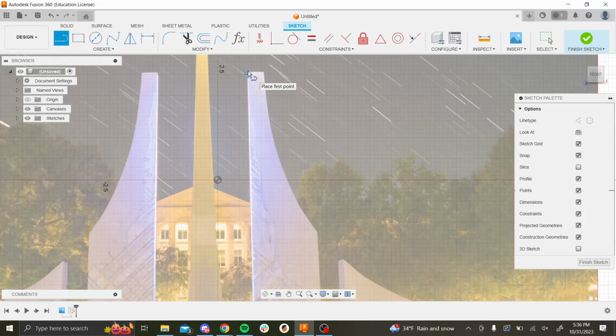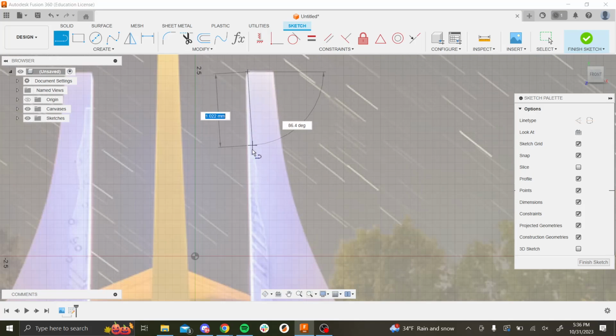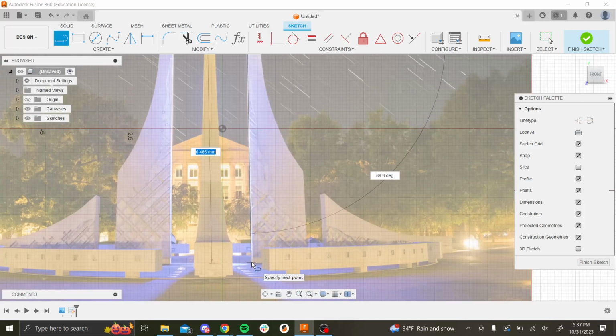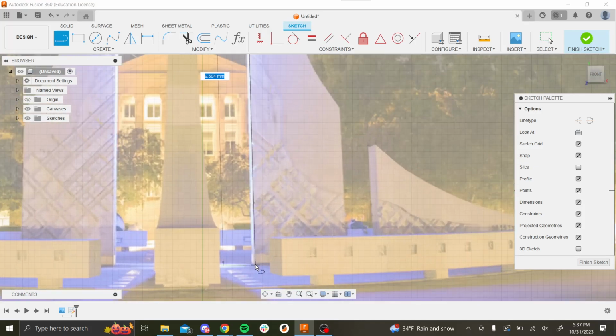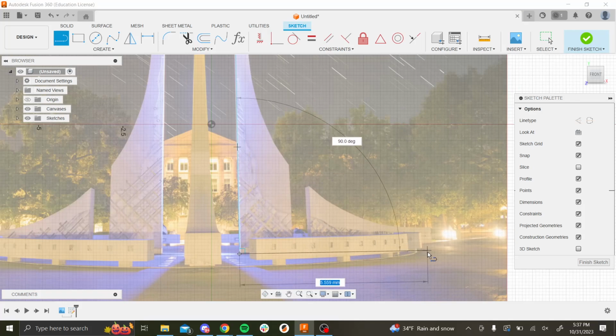I'm going to start by creating a vertical line from the top down to around where the bottom looks like it is. Again, this isn't super precise, just go until it looks close enough. Then I'm going to go all the way out, and you want the bottom line to be horizontal. This comb shape on the bottom means it's been constrained to the horizontal plane.